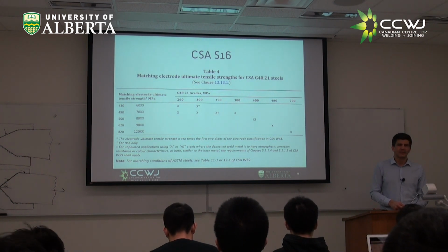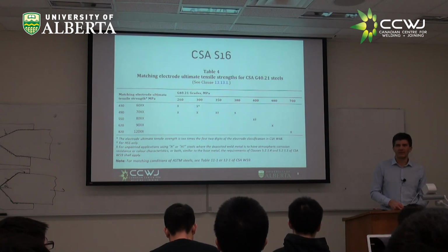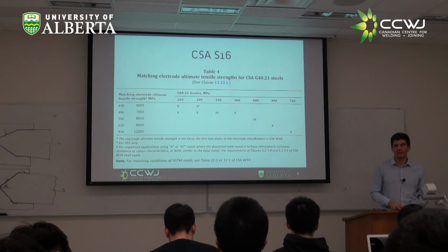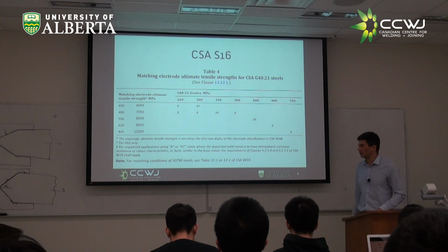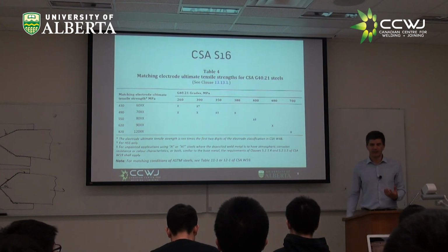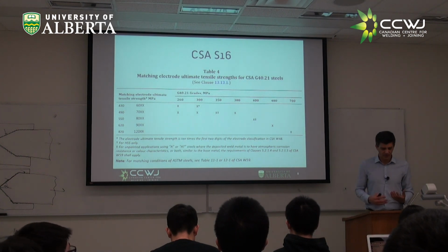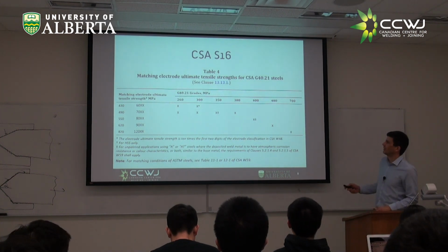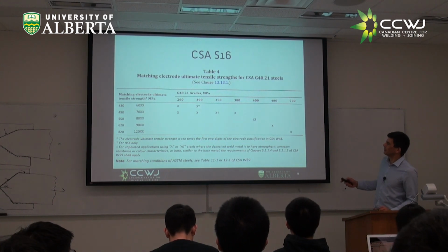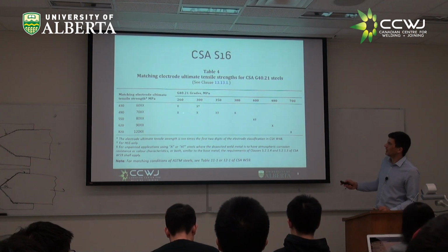No, because if a steel is stronger, probably has more alloying elements, right? If it has more alloying elements, probably it's more hardenable. And if it is more hardenable, probably when you weld it, you might end up with hydrogen cracking or something like that. So it makes sense to know. Most of these problems in welding come down to these things we would know, but we didn't think much about. All right, so this is the way we pick for what plate, what matching electrode we would have.